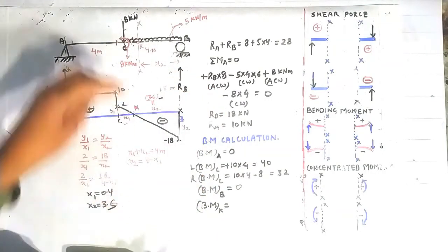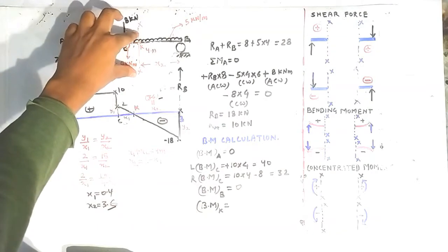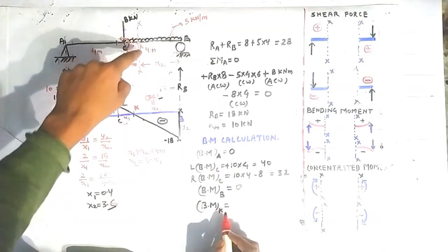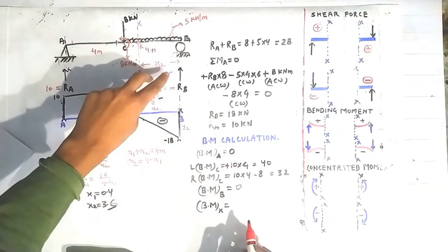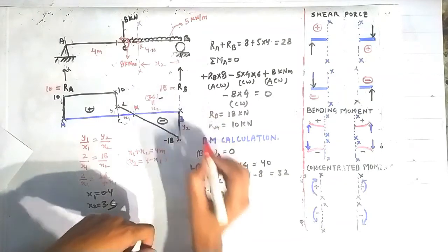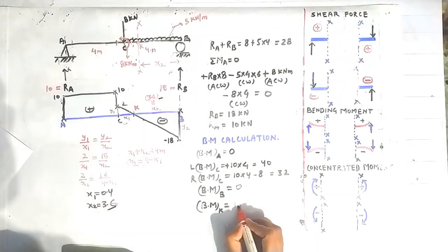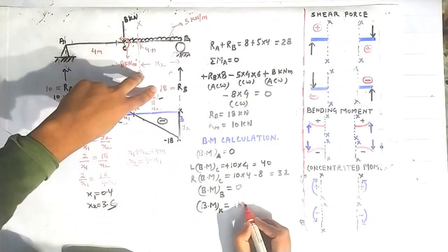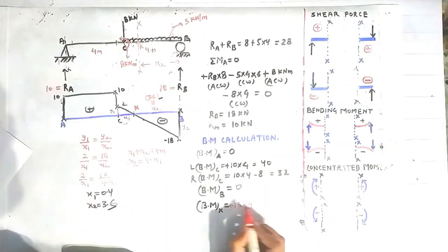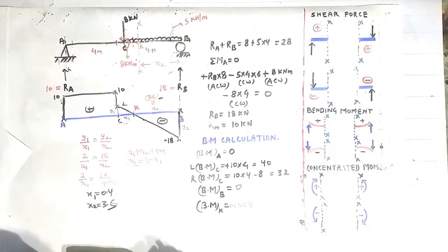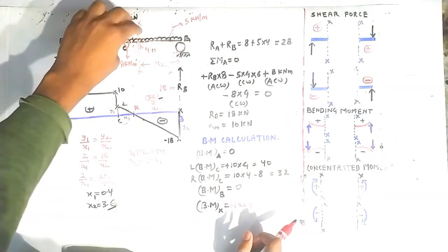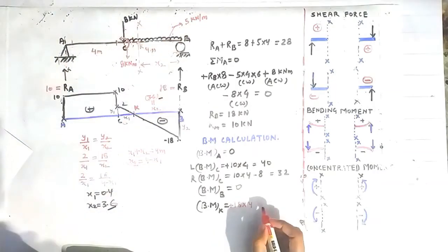Okay. Now we have to find out the bending moment at this section XX in order to find out the bending moment at this point K. So looking on the right hand side of this section, you can see that this RB is contributing toward a bending moment. The magnitude of RB is 18, and it is creating a sagging bending moment using this sign convention. Okay, and the bending moment because of this UDL, which is lying between the point K and B, will be equal to